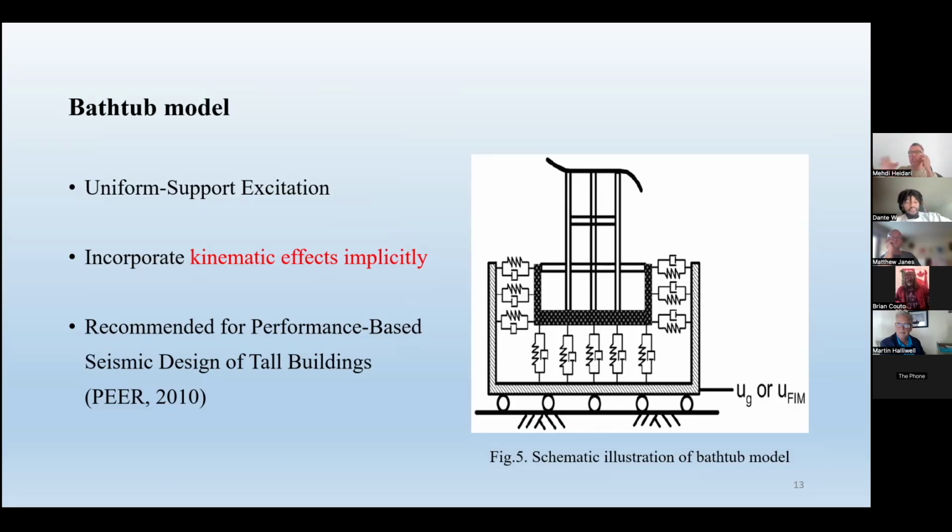These shell elements or membrane elements represent a floor, but they are not the floor. They don't have thickness, but they can simulate the behavior of that structural component. When it comes to soil, one approach is replacing the entire soil medium with some springs in your computer model.